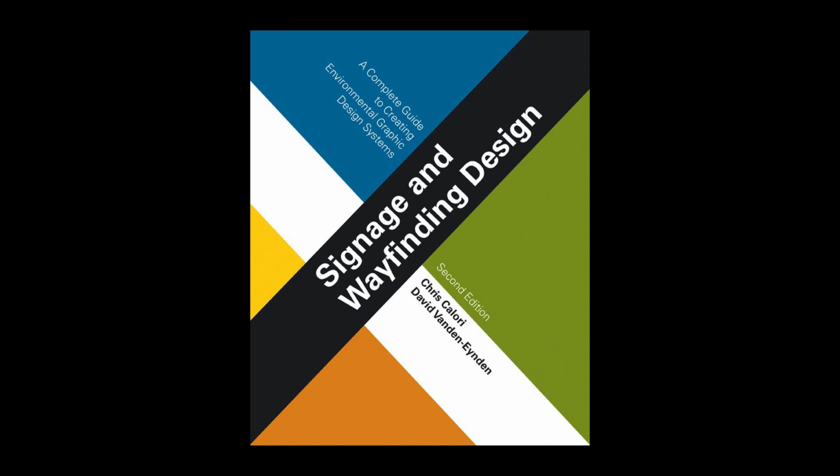The observations and conclusions of shop visits are documented in a memo or the meeting minutes, often with digital photos incorporated, which can be recorded by the EG designer, the contract rep, or the fabricator. In projects where the records of shop visits are produced by others, the designer should review them for accuracy and completeness before they are distributed to the project team.